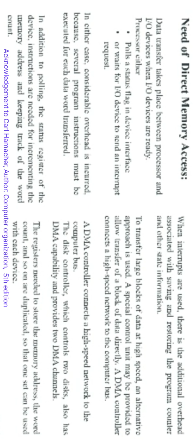To avoid this, with the DMA controller, a huge block of data transfer takes place without intervention of the processor. But the processor initiates the operation by giving the needed information to the DMA controller: how many words of data are to be transferred, that is the word count, the starting address in main memory, and the direction of transfer, whether it is a read or write operation.